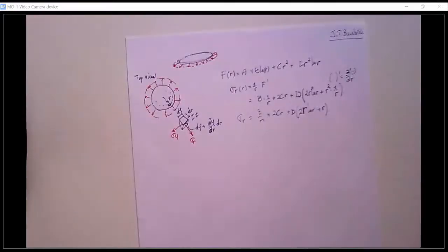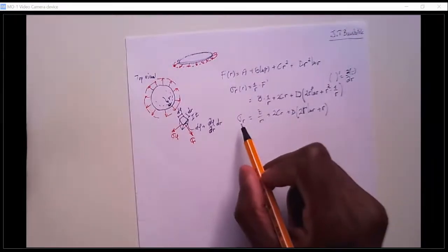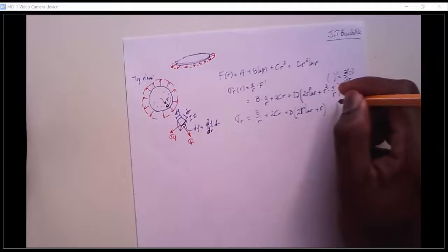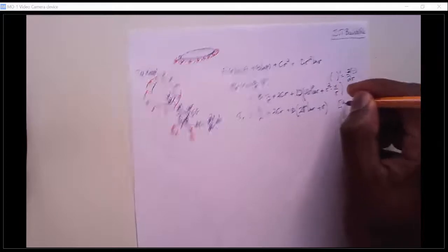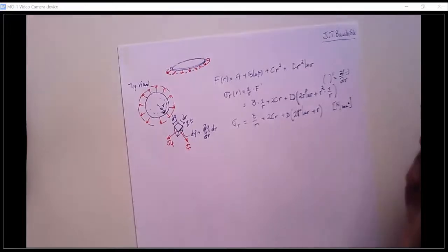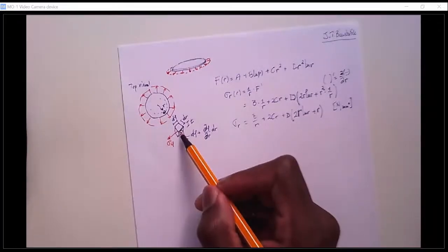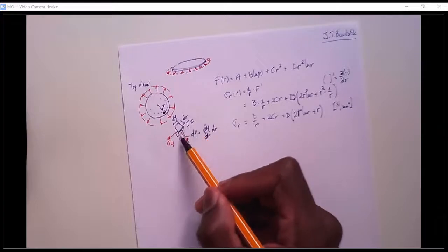By the way, here when we talk about stresses, there's a possibility to use the stress like sigma. The unit here would be something like Newton per millimeter squared, or we could also use a kind of line load. So if sigma is the force divided by the area, in this case the area could be t times